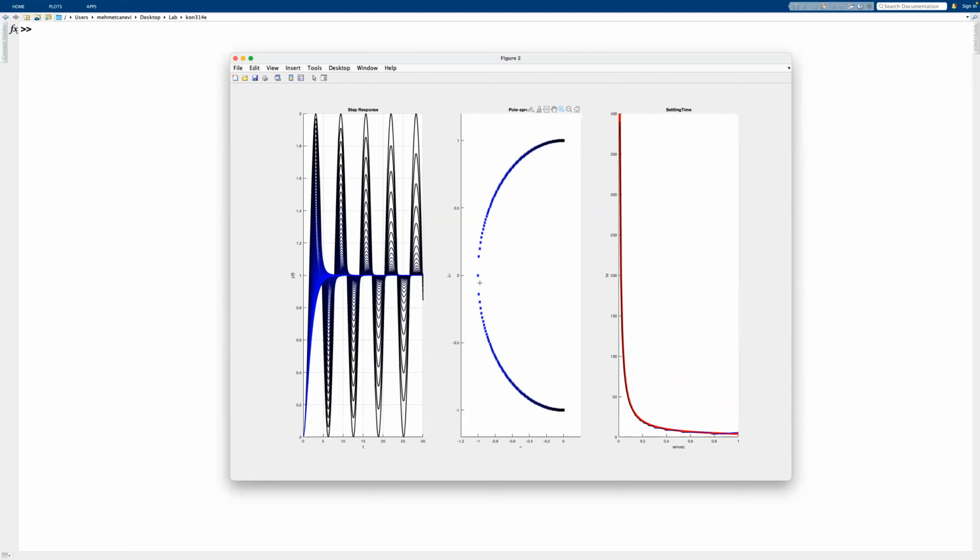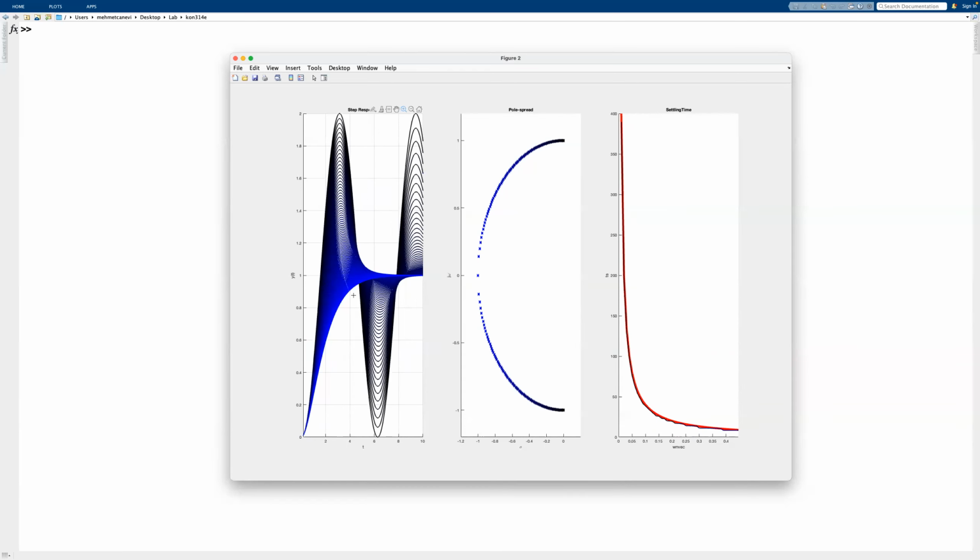Since we don't really want to use zeta equals exactly 1, if we have a certain overshoot in our mind, we're just looking somewhere on this line here. So we're okay with the settling time formula that we have here. Of course, we will have an overshoot formula too, but that's not going to be today's topic. But there's a formula and you can look it up if you really, really want that. So here we can see how smooth the transitioning is from sinusoidal waves into this first order kind of behavior.